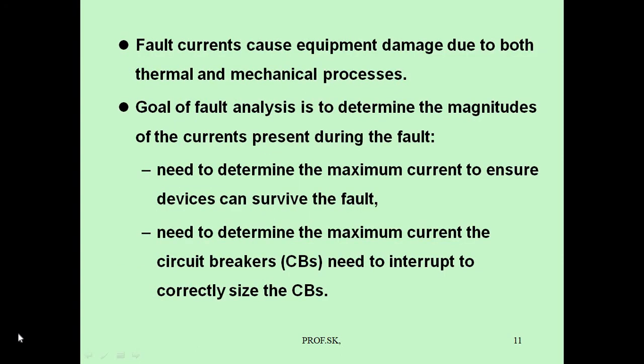Fault currents cause equipment damage due to both thermal and mechanical processes. The goal of fault analysis is to determine the magnitude of the current present during the fault. First, we need to determine the maximum current to ensure devices can sever the fault. Second, we need to determine the maximum current circuit breakers need to interrupt, to correctly size the circuit breakers.